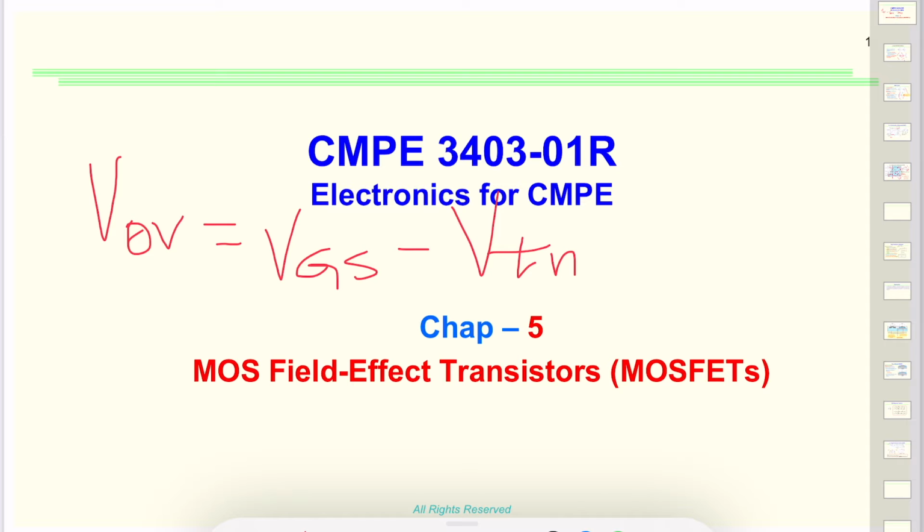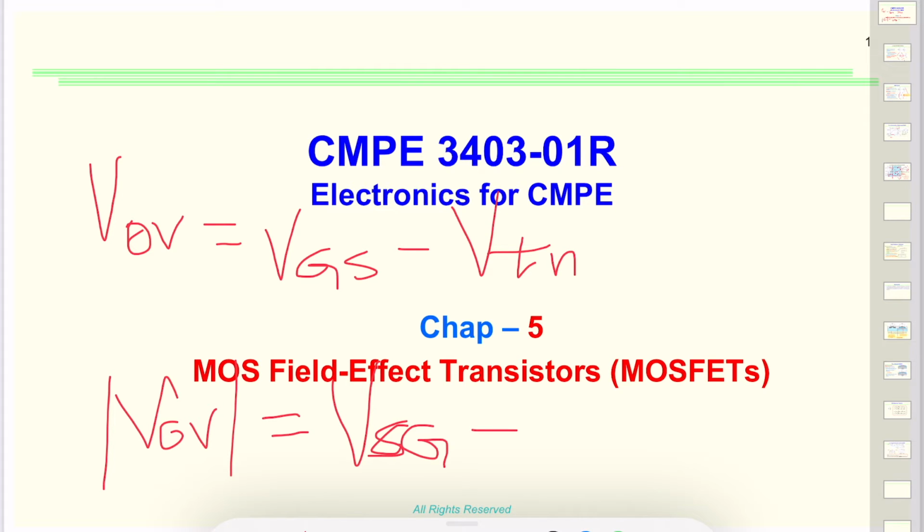When we are dealing with PMOS, we will use the positive values and the capital again, but we'll be using the VTP values for that. In many cases we will ignore channel length modulation, in that case, we will use lambda equal to 0.